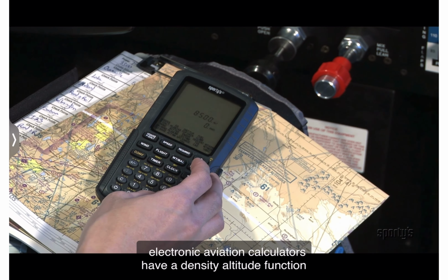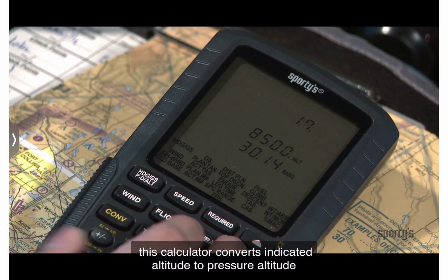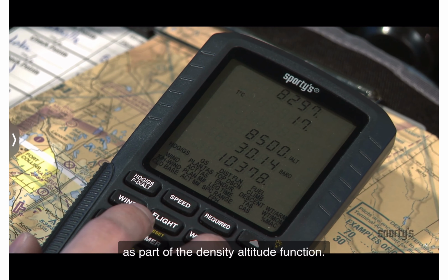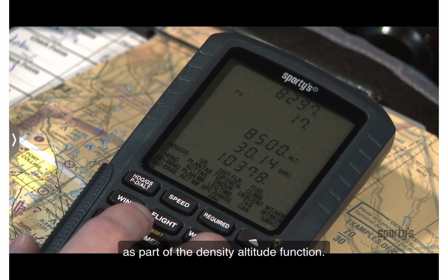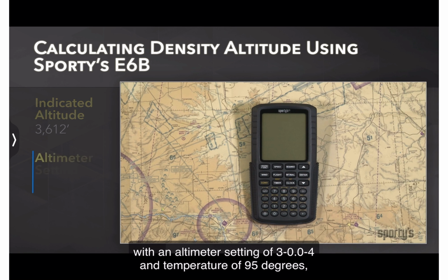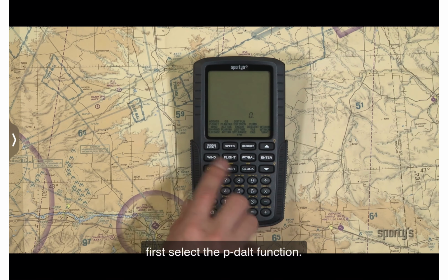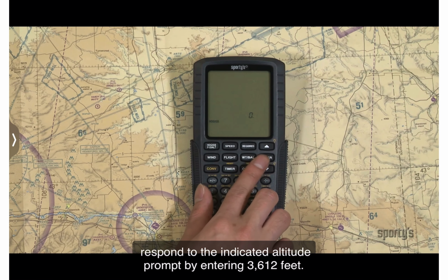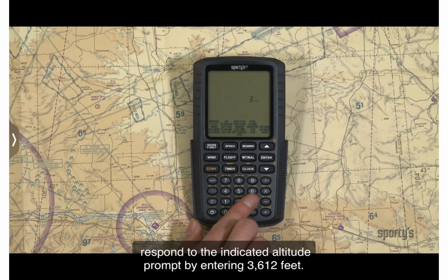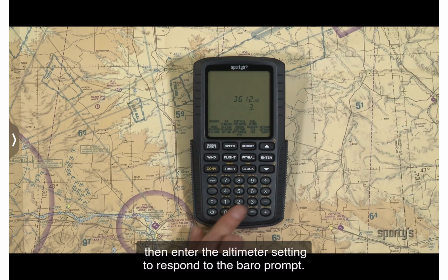Electronic aviation calculators have a density-altitude function that requires pressure-altitude input. This calculator converts indicated altitude to pressure altitude as part of the density-altitude function. To find the density altitude for an indicated altitude of 3,612 feet with an altimeter setting of 30.04 and the temperature of 95 degrees, first select the p-dalt function. Respond to the indicated altitude prompt by entering 3,612 feet. Then enter the altimeter setting to respond to the baro prompt.